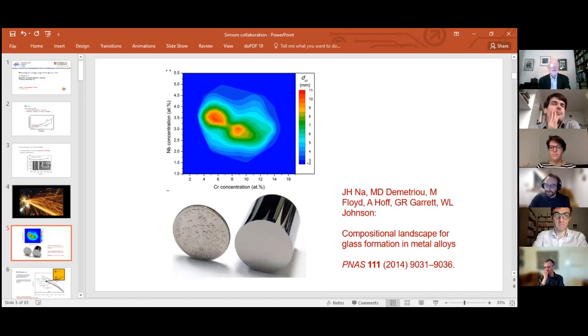It is clear that if you took a classical polycrystalline metal, which has a certain hardness, let's say, and you anneal it, let's say heavily deformed copper, pure copper, and you anneal it, it'll get much softer. The extent of the change of that yield stress of the copper is far, far larger than the extent of the yield stress for the treatments that we've managed to do with metallic glasses. So the treated metallic glass is still pretty hard.